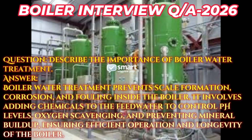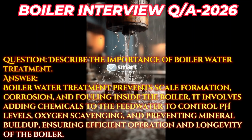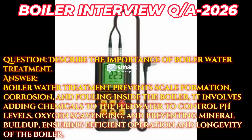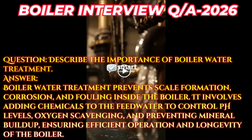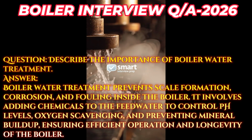Question. Describe the importance of boiler water treatment. Answer. Boiler water treatment prevents scale formation, corrosion, and fouling inside the boiler. It involves adding chemicals to the feedwater to control pH levels, oxygen scavenging, and preventing mineral buildup, ensuring efficient operation and longevity of the boiler.